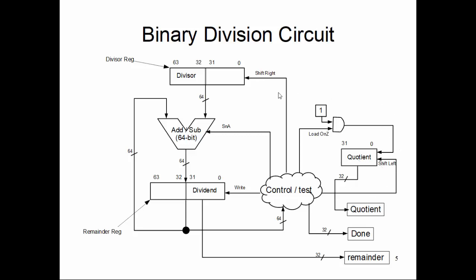All this quotient, divisor, dividend are the data crunching part. And as a philosophy of circuit design, we should not directly use a control signal as data as well. That's why we introduce a little extra circuitry here to select between 0 and 1 depending on a control signal.